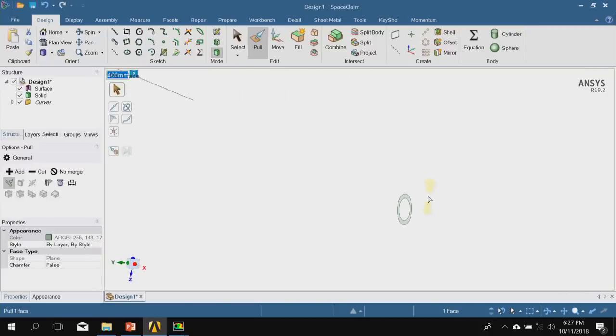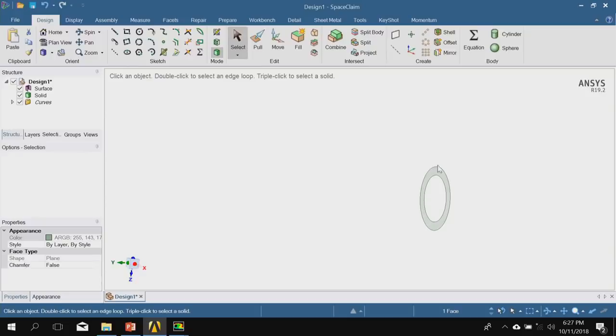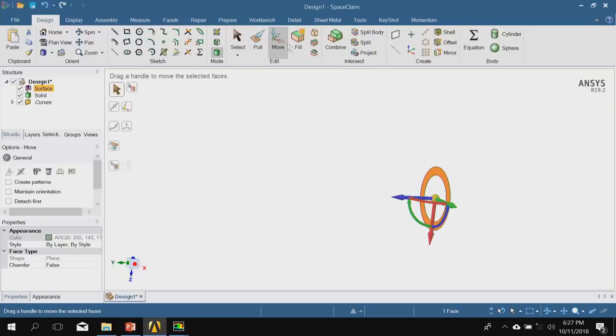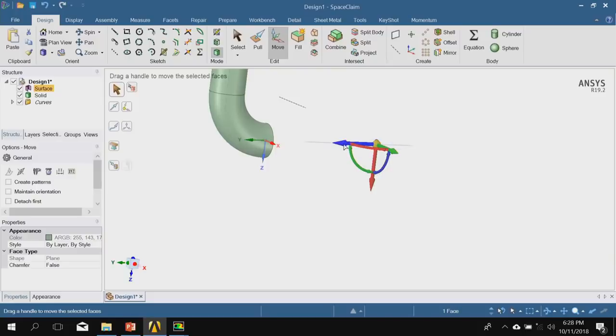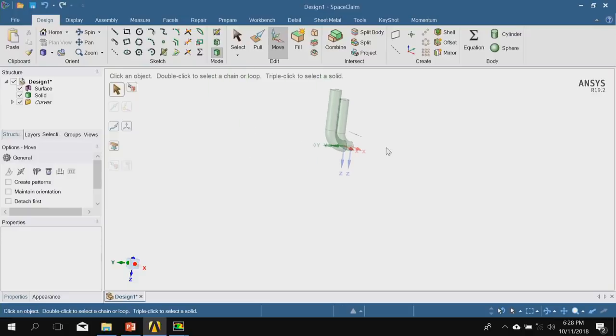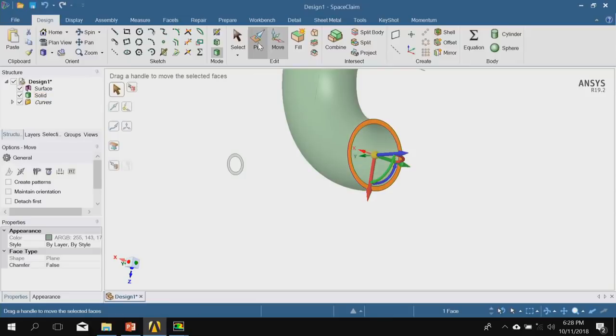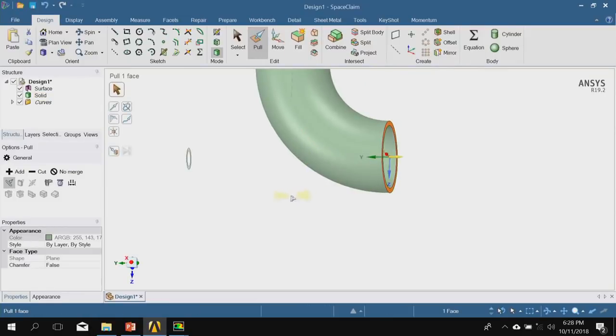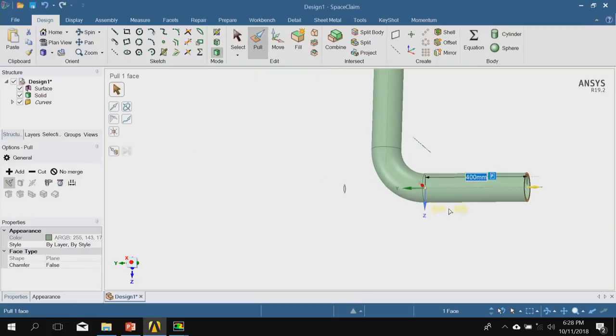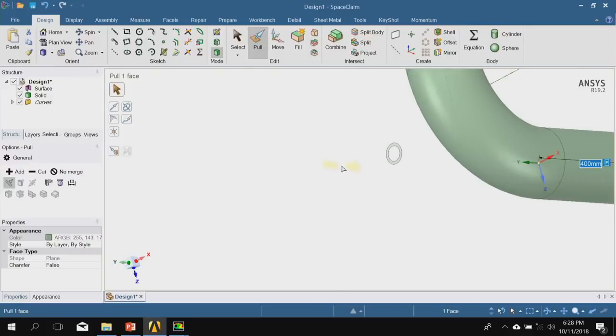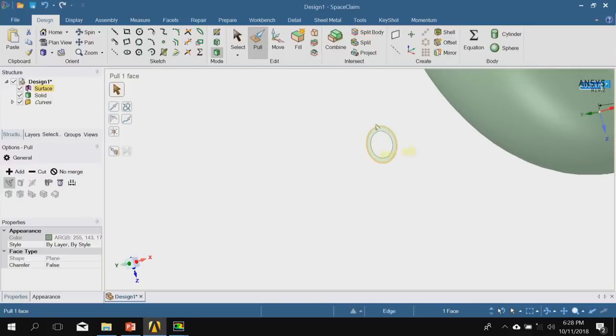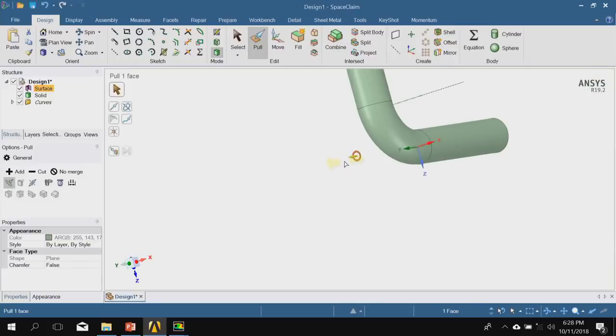I'm going to move this out of the way. So I'll select it here. Use the move operation, and I can move this quite arbitrarily. I don't have to be very precise. I can move it over here. I can now generate the second leg of the pipe. Select pull. Move by 400 actually. And as you can imagine, I can do something similar to this annular region to create a small pipe. So I have this mixing elbow.